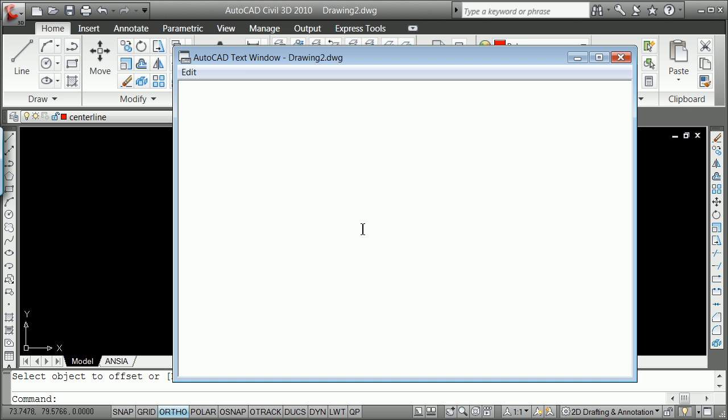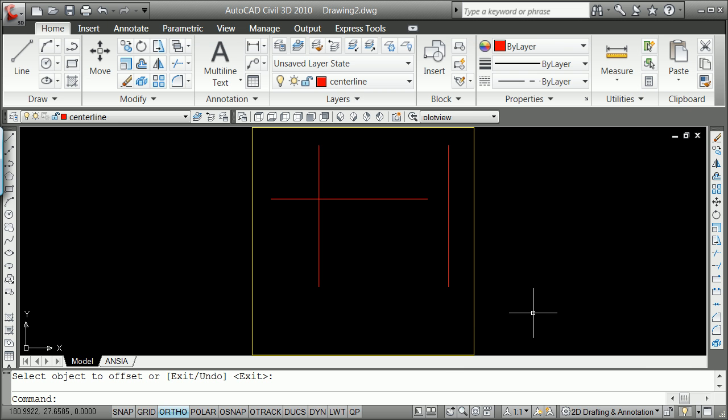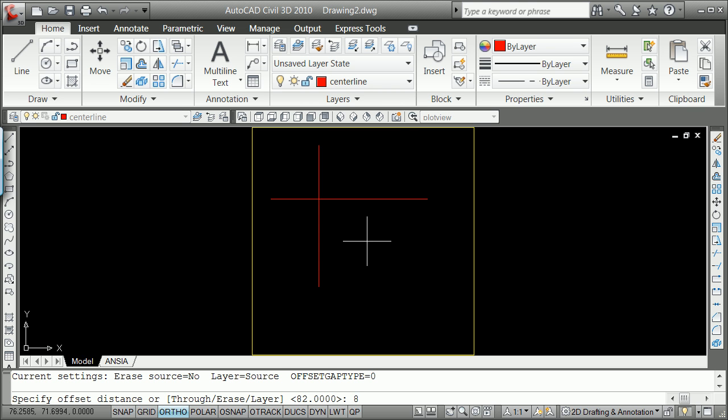And I'm going to just double check that I offsetted 82, and so I did. It looks a little off, I've had 140 by 140. I'm guessing that my box here is not 140 by 140 if I've offset 82. So I'm going to go ahead and explode my box, list it, and it is 140, and so I'm going to once again erase that, even though it looked correct when I did it. Offset 82, and I guess that works for me. So I've got 82 this way.